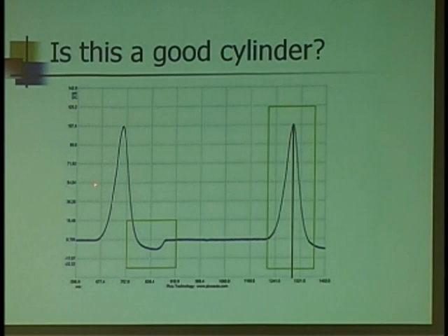Because when we got to the top, we compressed the air charge. When we compressed it and stayed there, we lost some of the volume. So now the pressure is going to change much more rapidly and drop into vacuum. And of course, not to mention that you could actually measure the same cranking pressure that you would with your traditional gauge. You got all the information right there.